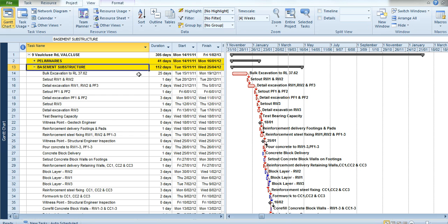With this builder, they requested that we produce the task names over on the Gantt chart itself. It does make it a little bit easier to read. We have highlighted in red the critical path. Each of these are the critical items. If any of these items is monitored and is going past these times or shortening of these times, that will affect the duration of the project, which is critical to the end date on the project.